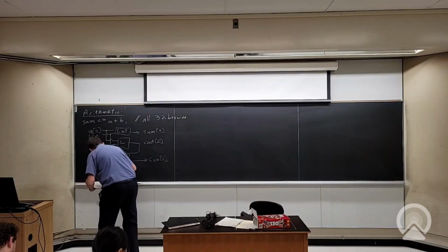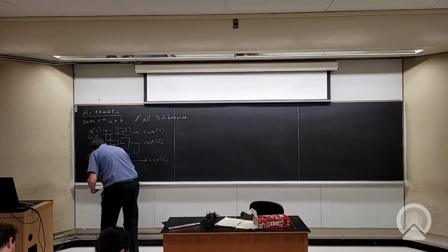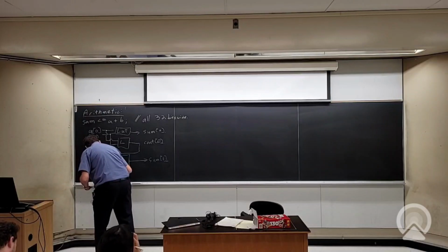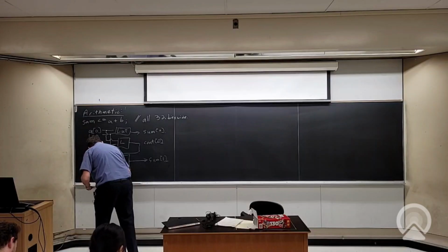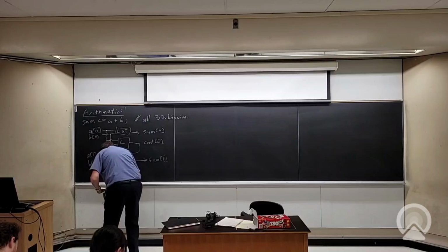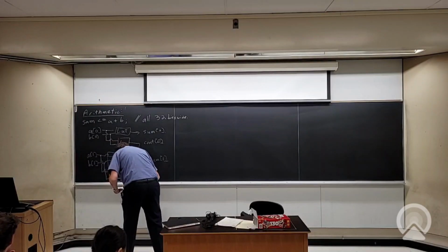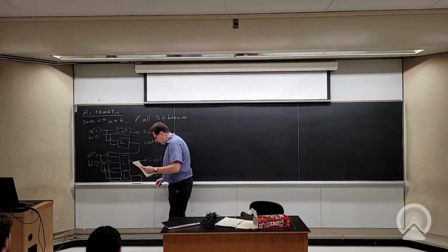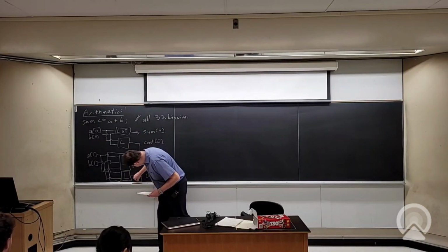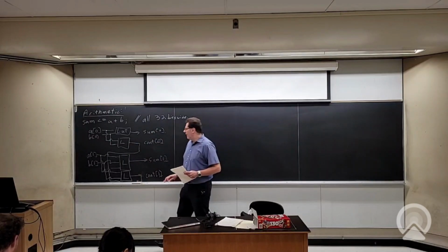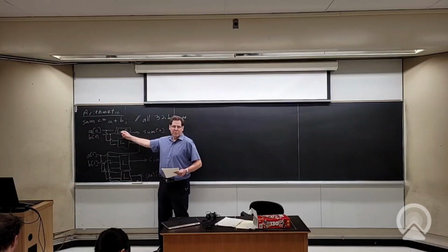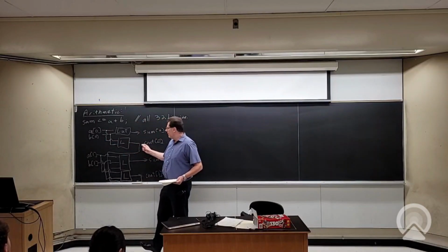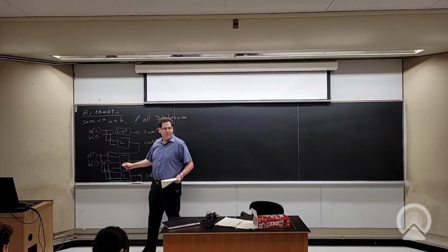Try that pretty messily. Let me erase that. Okay, so I'm not going to draw this whole thing. That's like the first 2 bits. So I take A of 0, B of 0. From those I compute sum of 0. A of 0, B of 0. From that I compute C out of 0. C out of 0 goes down to my next bit in the adder.